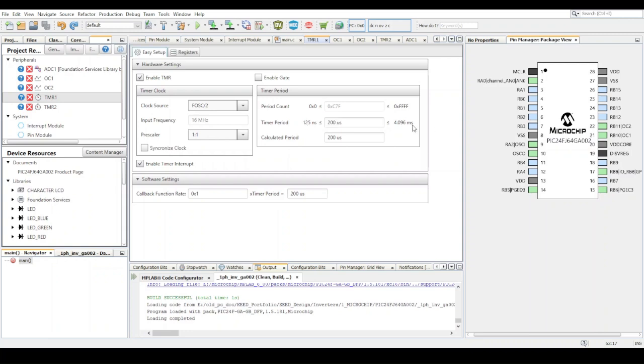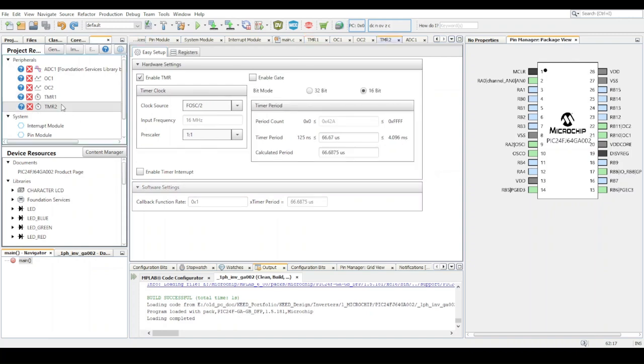And that's about it for the initialization of the firmware for this. Just to recap, first you want to set up the switching frequency for the MOSFETs, which is 15 kilohertz, and then the period is going to be 66.67 microseconds. Then set up timer 2 for this. You can also use timer 3. This particular microcontroller has a limited number of timers. It does have 5 timers actually, but I believe for the PWM it's just timer 2 and 3.